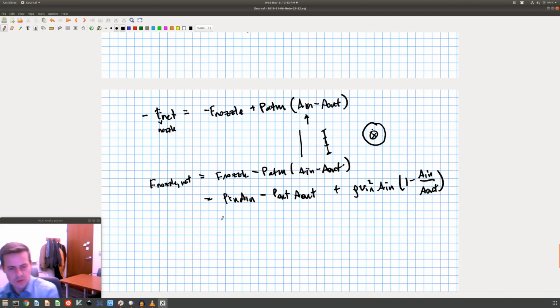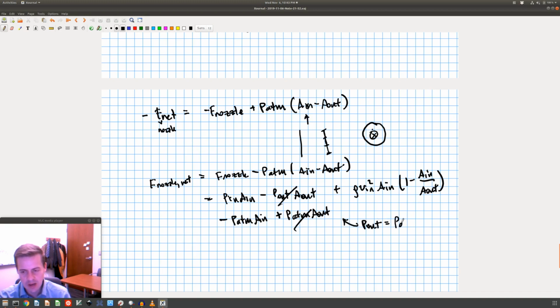And now I'm going to subtract P atmosphere A in plus P atmosphere A out. And look, P out and P atmosphere I said were the same, so that guy cancels there, because remember P out equals P atmosphere. Now I have P in minus P atmosphere, which is going to give me P in gauge times A in.